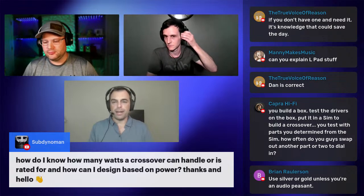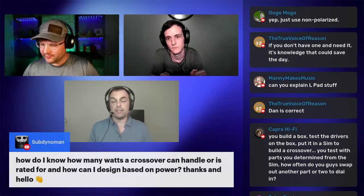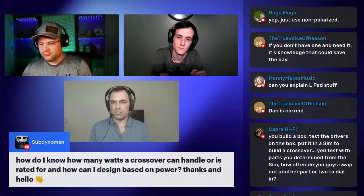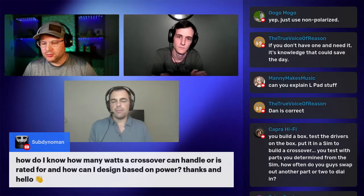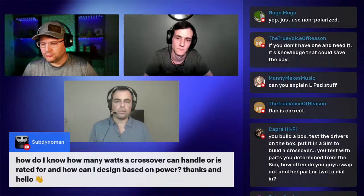I think most, even $1 capacitors are going to have enough voltage. They're going to be able to handle most of the power. The inductors, like Cameron said, maybe if you're in a pro audio setting and you're using really cheap inductors, you might melt them. But generally, resistors are like 10 or 12 watts rating. So generally, we only use those on the tweeter section. Well, I shouldn't say only. Definitely use them in a woofer section, and mid-range maybe. But they don't see a lot of power in the woofer crossover because they're usually on the second pole or on a notch filter or something like that.